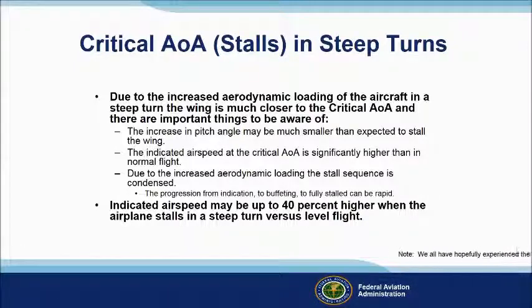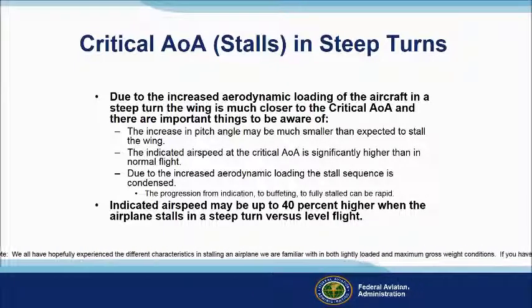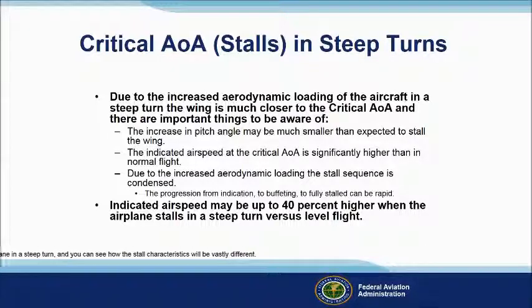Note: we all have hopefully experienced the different characteristics in stalling an airplane we are familiar with in both lightly loaded and maximum gross weight conditions. If you have not experienced this, you should, because depending on the airplane, stall characteristics can be very different. Now, consider effectively doubling the maximum gross weight of the airplane in a steep turn, and you can see how the stall characteristics will be vastly different.